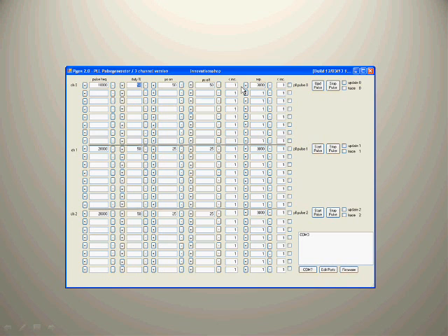Repetition rate means that this on-off pulse, defined by frequency or pulse-on and pulse-off times, is repeated 3000 times in our case. The so-called pulse train. You can combine in a single channel up to 8 of these pulse trains. For example, in the second line you put in 20,000 Hertz, 30,000, 40, 50,000 Hertz, always 3000 repetitions, and then